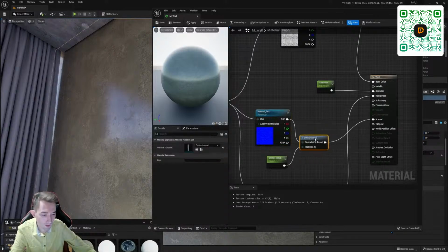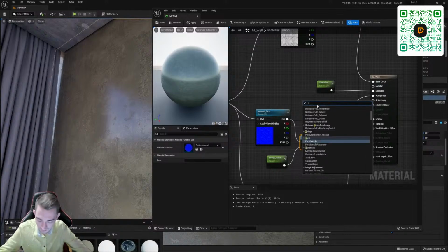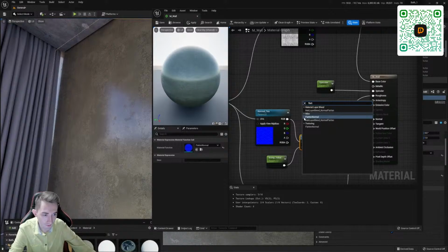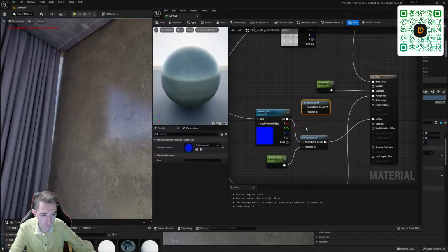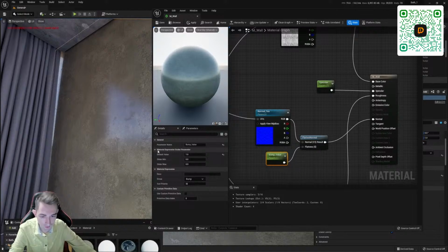We connect it to the flat normal node. Flat normal: just right-click on an empty space, enter flat normal, and find this node. Here it is. We also connect a parameter to it that changes this kind of bump force. At 0, we have extrusion going on, and more precisely, we have extrusion working both in the opposite direction and in the one that is needed.